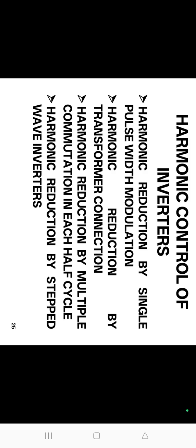This type of modulation in which the output voltage has only two levels during the half cycle is called two-level modulation. Inverter 2 is so operated that its output voltage is VL2. It is observed from the VL2 waveform that the output voltage level is positive, 0, or negative during the first half cycle. Therefore, inverter 2 is operated with a three-level modulation. The load waveform shows that the amplitude of the output voltage is 4 Vs and the waveform has 4 steps.